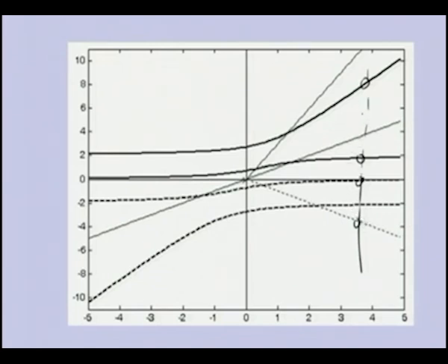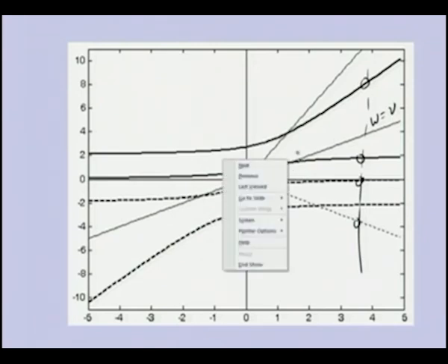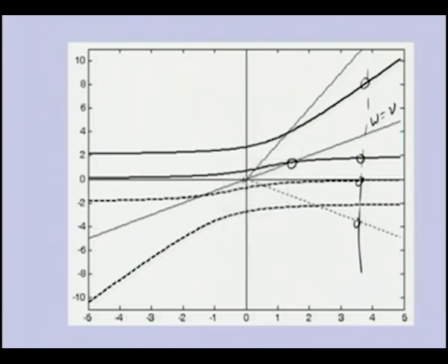Regarding the critical speed, this line is the omega equal to nu line, and the intersection of this will give the first critical speed, here. This line is not intersecting the second line, so there is no critical speed corresponding to this.